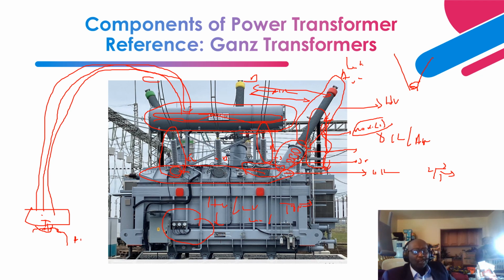For the hotspot temperature indication, it uses a dedicated CT that is located in the low voltage winding, let's say phase B, that is connected to the load. So the CT is measuring the load current. That load current is connected to a heater, so the heater builds up heat, and the temperature is measured from the heater. And a gradient is added to achieve the hotspot. So that's how the hotspot temperature is achieved.